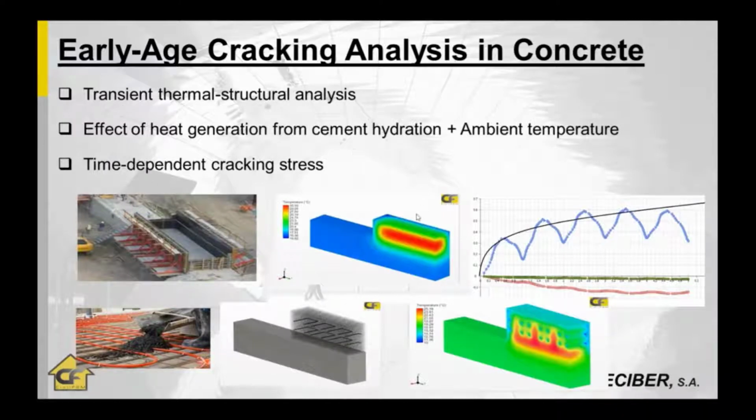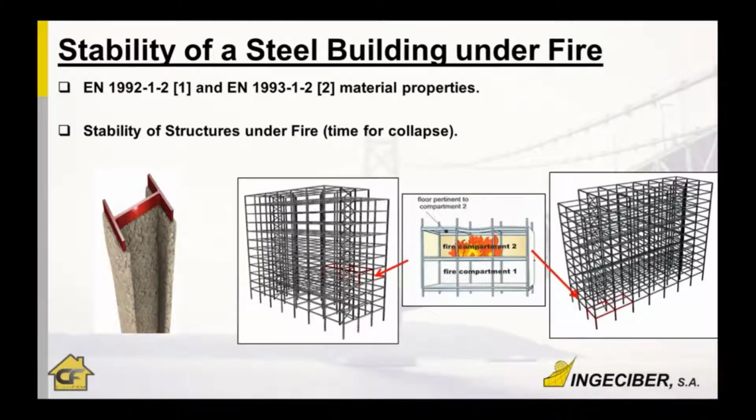So with this model, we can check that at these zones, the stress on the concrete, the thermal stresses, are over the cracking state, and we can see in those days where the cracks develop and find in the model those crack developments, the same way we saw before. This is an example we can solve with CivilFEM.